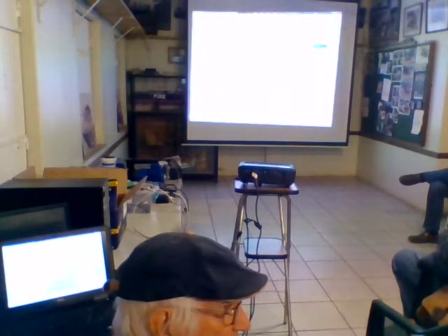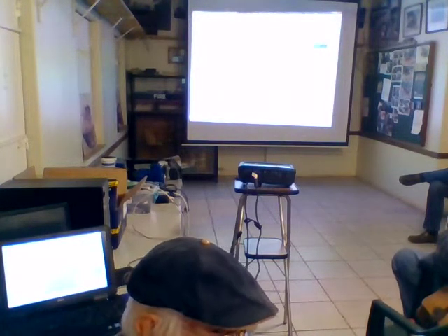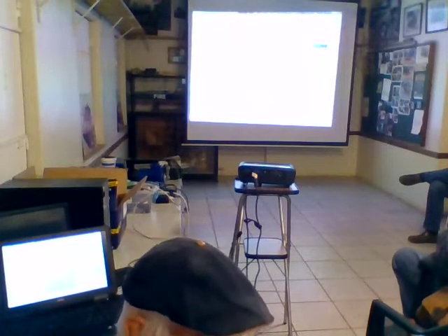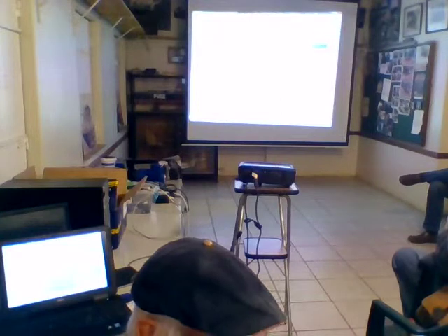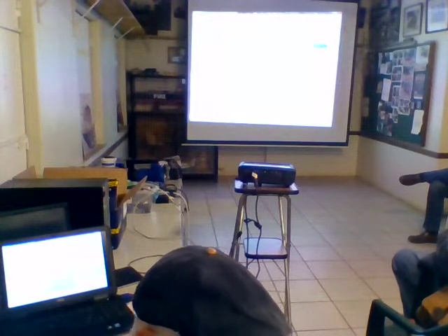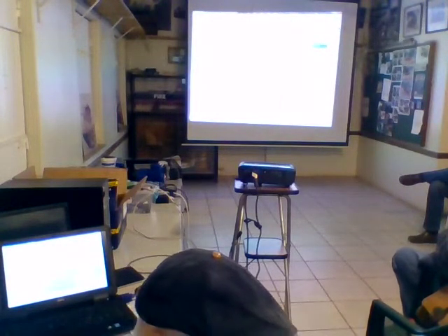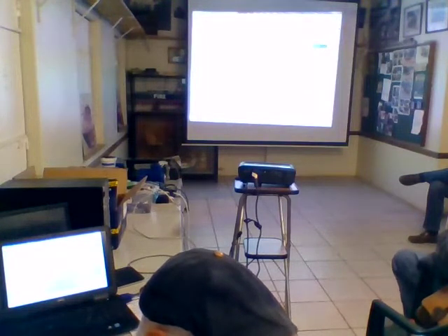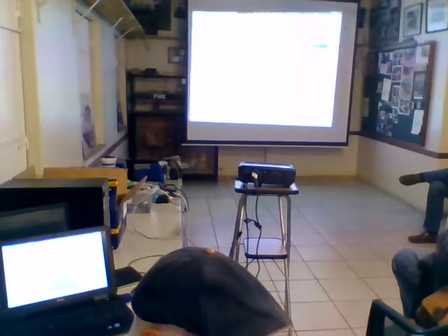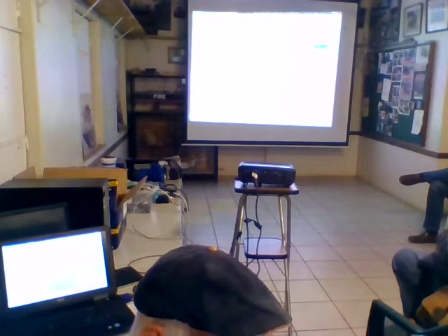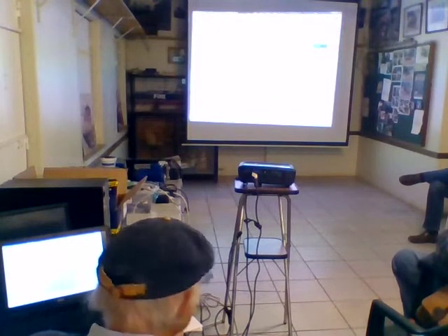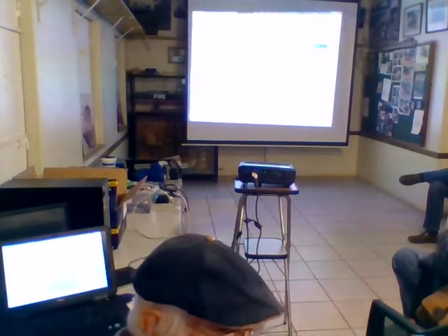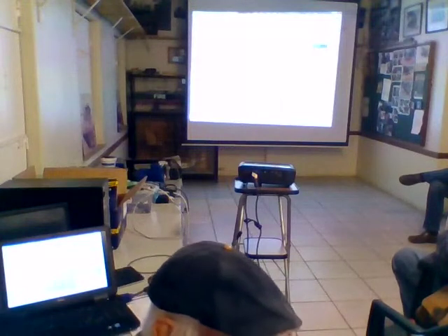And the machine is heavy, as he mentioned. Heaviness is always an advantage, but it's a costly thing. We can make it a ton if we want to, but we don't want a machine that weighs a ton if we can make it for less. The other thing is the 200 kilos spindle that can also turn, the machine with a flywheel on it. Yeah, but if you make this heavier and thicker, you need a bigger motor. Everything goes up and up. Then you need a bigger drive. You need more current to move it, accelerate it, and so on.